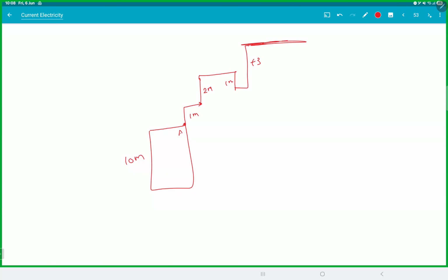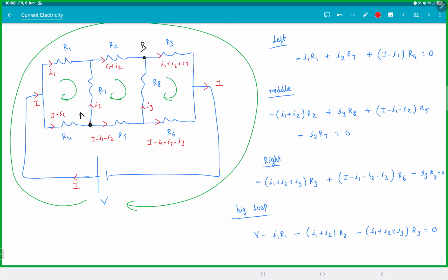So this is Kirchhoff's loop law, right? You can actually use it partially also, from one point to another point. Now see, if I start at point A and go like this, I'm going through R7 in the direction of current. So what will happen? It should drop. So VA minus I2 R7. Then I went through this, which will be minus I1 plus I2 R2, and I reached VB. Is it making sense how I'm writing? You need not complete a loop. You can start at some point and stop at some point.